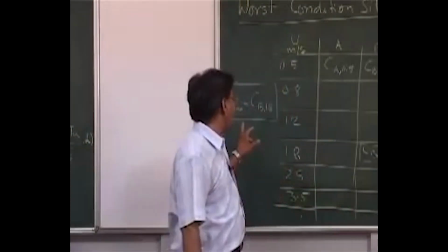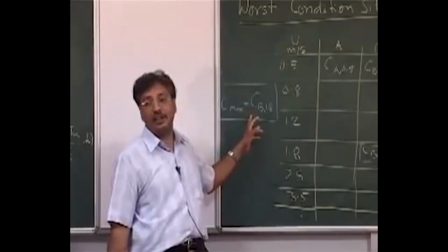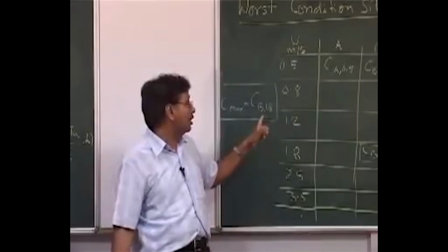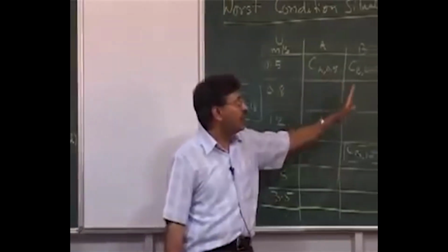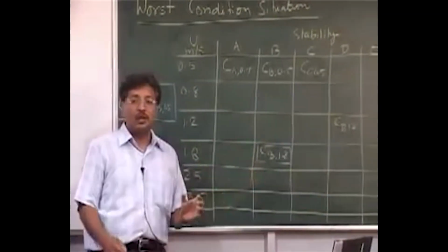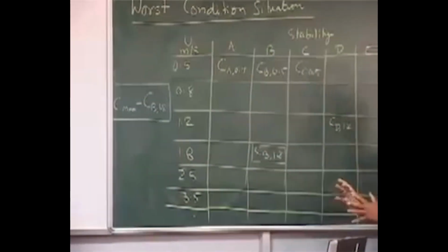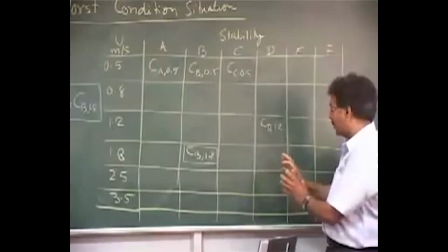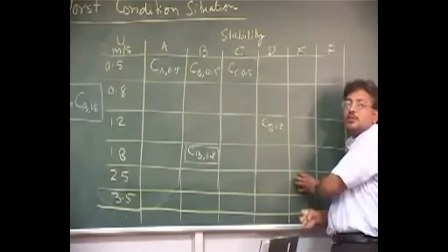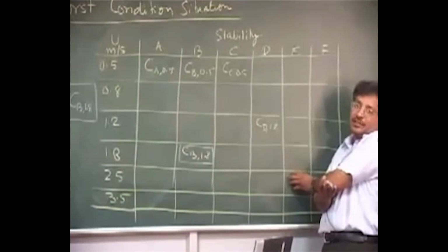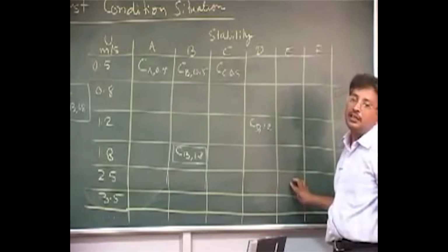Suppose that maximum concentration came out to be higher than this value. Then you can run another analysis to find out which set of situations has the highest probability. Then you come out with the situation most likely to occur, with a probability of, let's say, 50 times in 10 years. So then you say, all right, let's design for this situation.